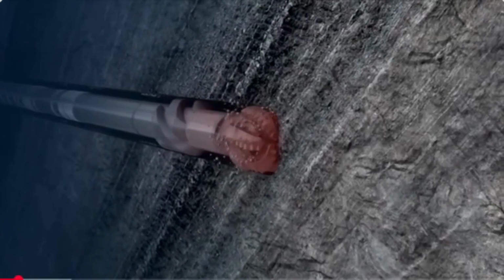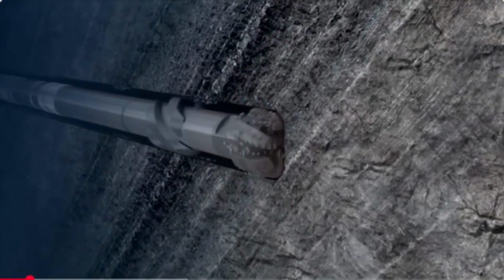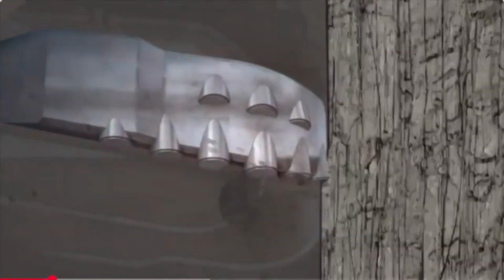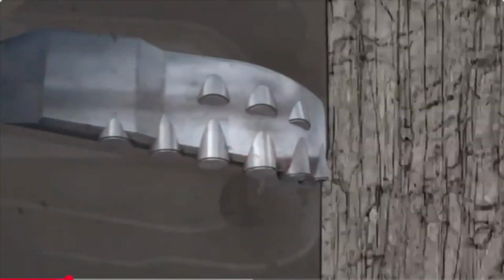The bottom hole assembly is exposed to large torque variations and vibrations as the bit progresses through constantly changing rock types. Consequently, the bit will stick and slip, resulting in shock loads on vital downhole components. Modern drill bits are optimized to cut the rock driven by weight and rotation, controlled from the surface of the well.